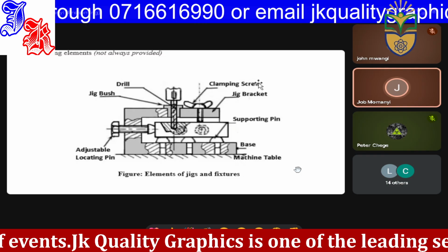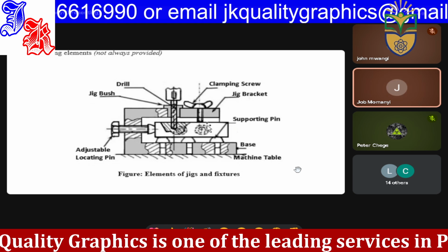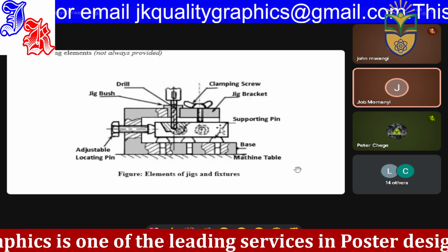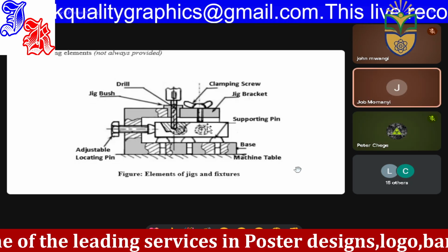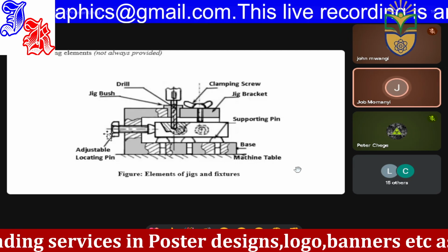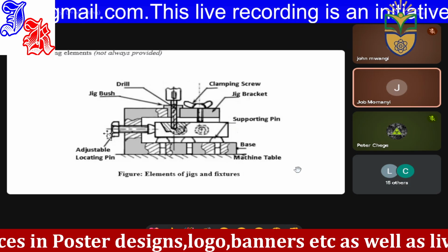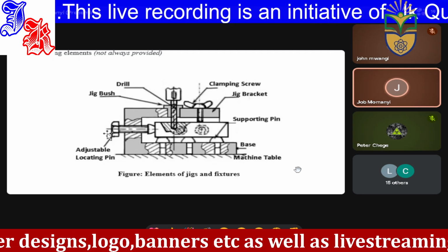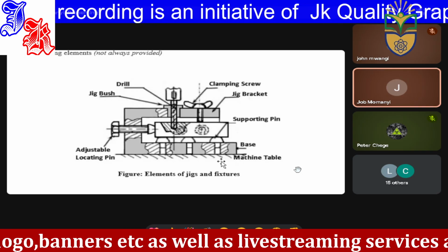Now we have a clamping screw, which by turning, probably if you turn clockwise, it extends. While it extends, it presses on this workpiece. That is clamping. By doing anti-clockwise rotation, that's unclamping. So we have also an adjustable locating pin to ensure that the workpiece does not translate in the horizontal direction. So it is secured or located using this adjustable locating pin.